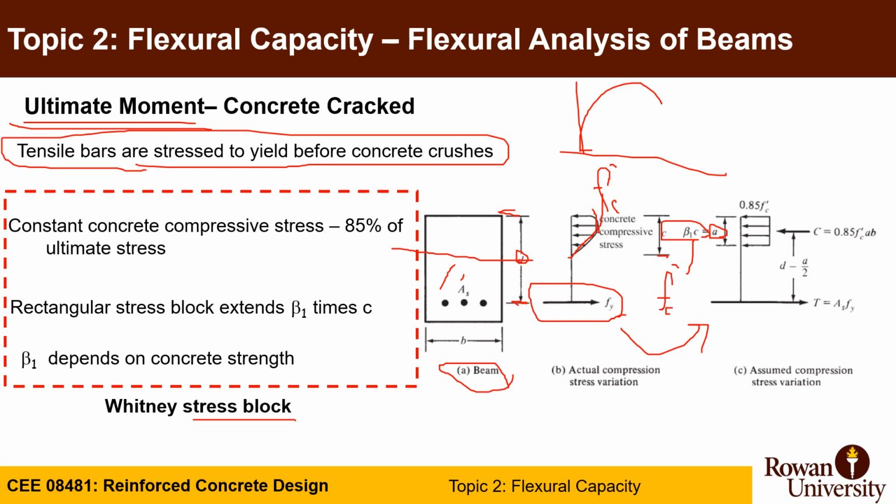Instead of distributing stresses over c, we are distributing over a, and we also use 0.85 f'c to get an equivalent area to this curve.